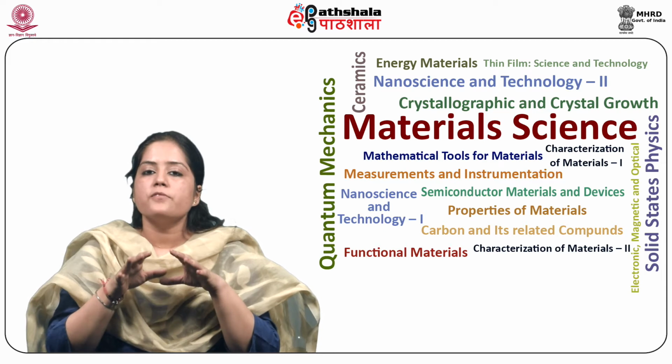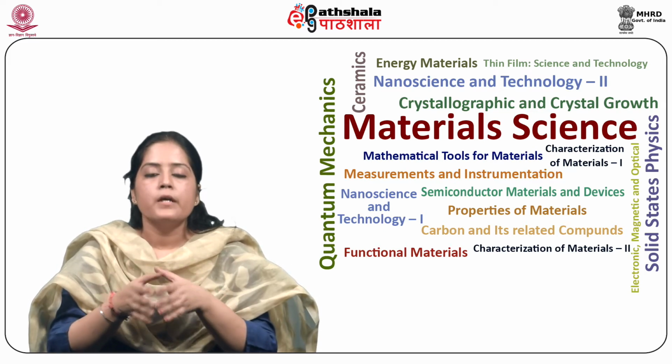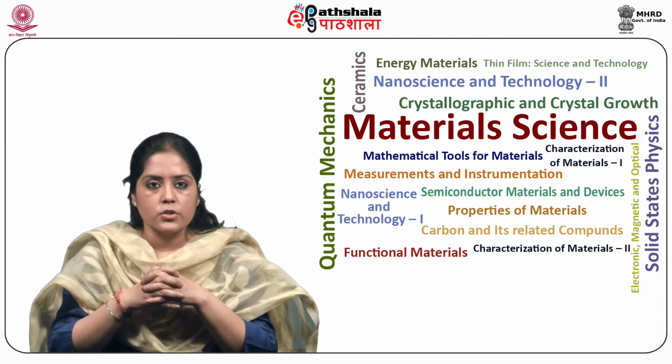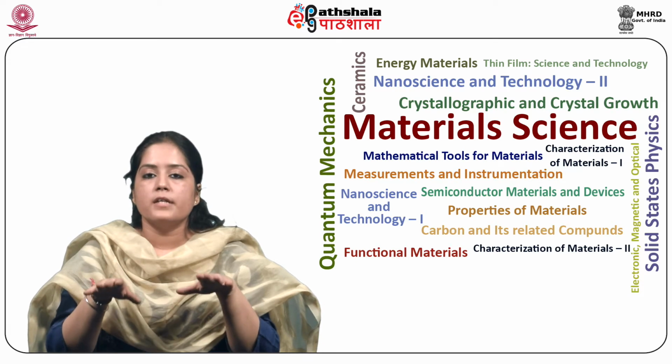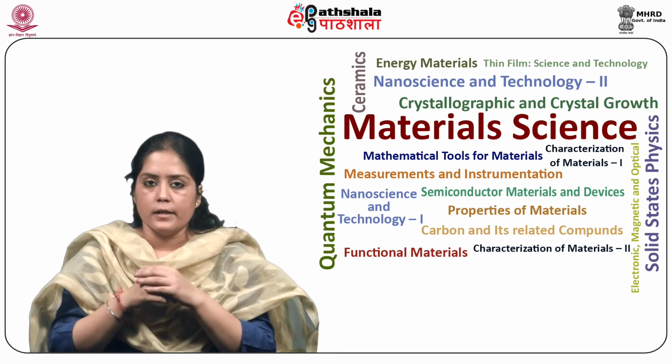For surface functionalized SPR bio and chemical sensors, the sensitivity depends on the effective refractive index change and the surface refractive index change caused by surface interaction binding.